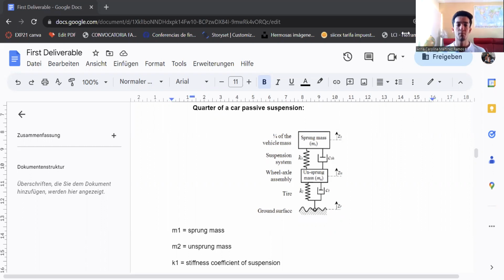But first, what are suspension systems? Suspension systems are highly important in cars due to all the functions they have while the automobile is moving. The main functions can be highlighted as maintaining the wheels in constant friction with the contact surface and ensuring the driver's safety, reducing the impact effects on the car cabin caused by the irregularities on the road, supporting the weight of the vehicle, and stabilizing the movement of wheels, making it easier and safer to keep the vehicle in the required direction. For the commercial solutions, there are three types.